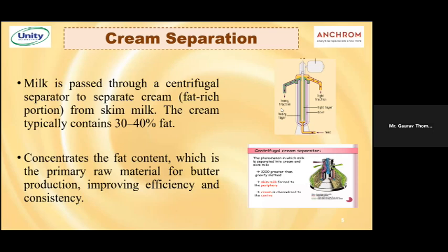Those are centrifugal separators. These separators agitate the milk inside and separate the liquid and the cream part. When you agitate the milk, the fat gets collected at the top of the vessel, and the liquid, which has lactose, moisture, water and other hydrophilic substances, is left behind. Okay, so that cream is separated.